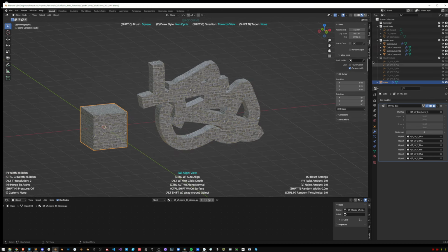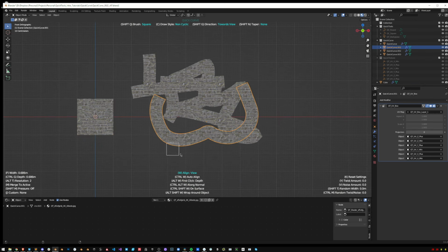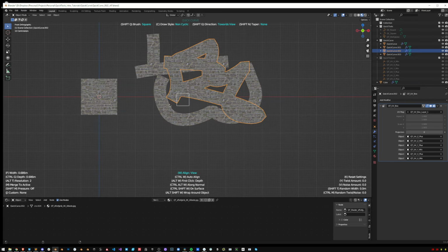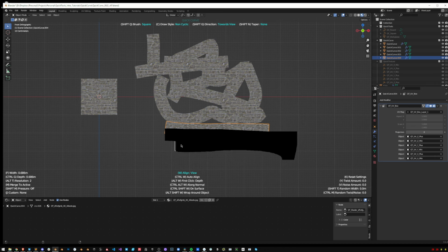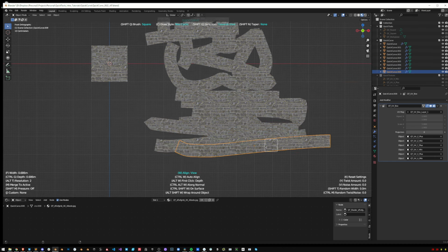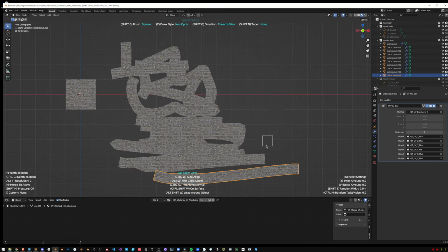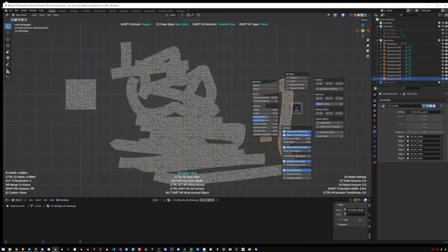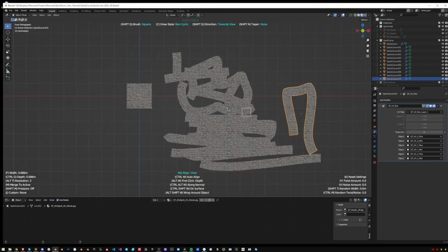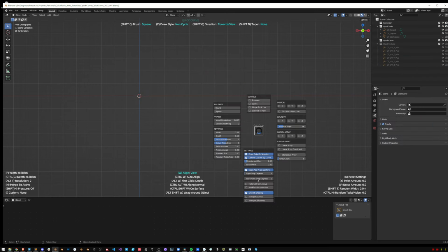And that's the reason that setting is here in QuickTexture. If you want more information on this force procedural thing, just watch the QuickTexture tutorial. But basically, once you have that set up, as long as you have the object selected, you can draw with it and you will have the material. That's how I did the wooden planks in the old QuickTexture video, and I use this feature all the time. This is really cool. And this works for material from active. This can also work for the other setting in there, which was modifiers from active.